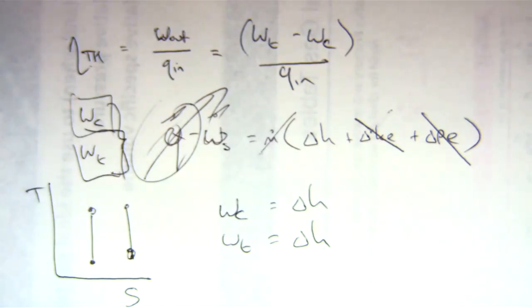Both CP and CV delta T rely on delta T. So why can't I use CV delta T? The answer there was because it's enthalpy. CP connects temperature and enthalpy. CV connects temperature and internal energy.